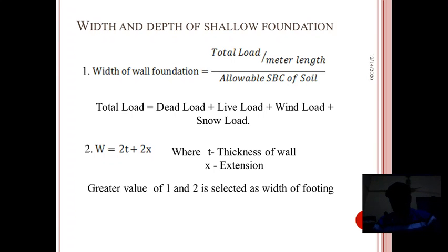First criteria you can observe by calculating total load per meter length acting on the structure and allowable SBC of soil, which is already calculated by using load test method or plate load test. So here total load includes dead load, imposed load or live load, wind load and snow load. Sometimes we will consider seismic loads.